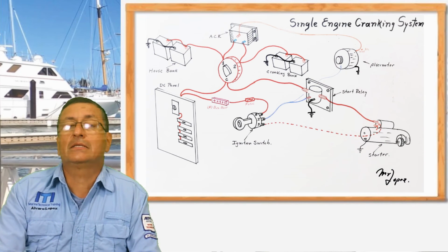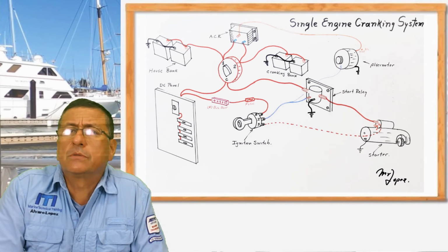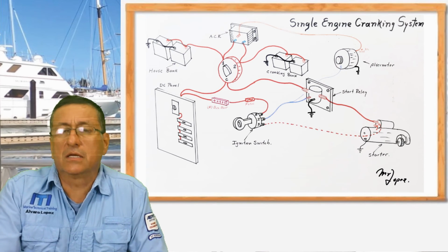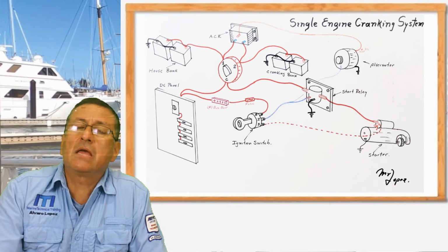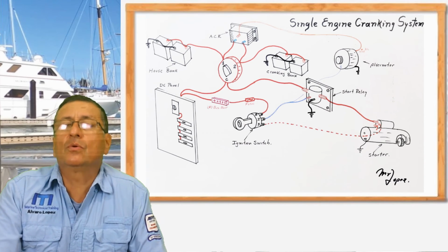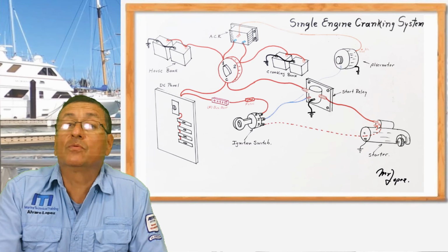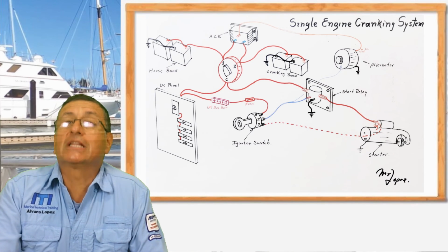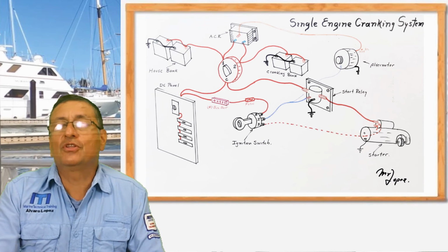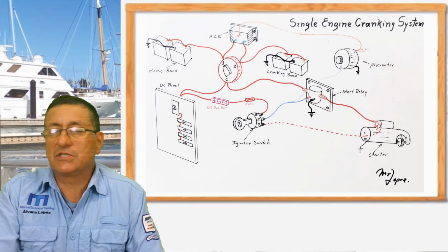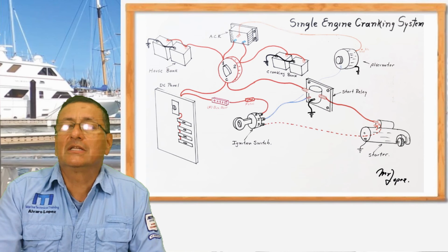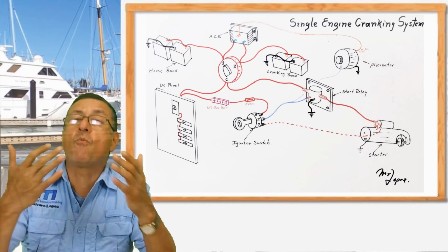We are going to analyze the start motor in the laboratory. We are going to check it in the vise, on the table. We are going to connect the start motors, and we are going to analyze if the start motor is working properly. And we are going to check the procedure to verify if the start motor is working well, the procedure to check if the brushes are in good condition, or if the stator is good or not good. This is part of this laboratory. This is a wonderful laboratory.